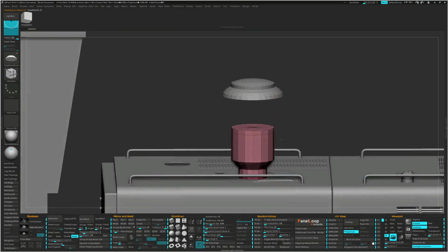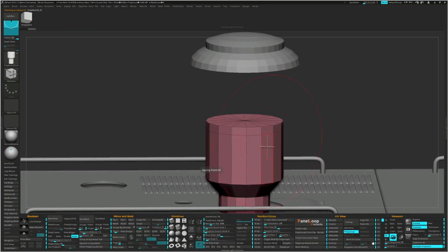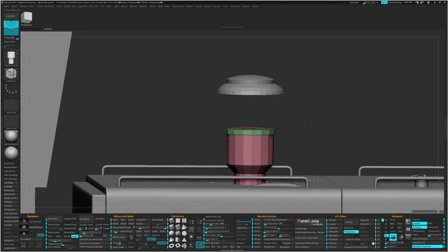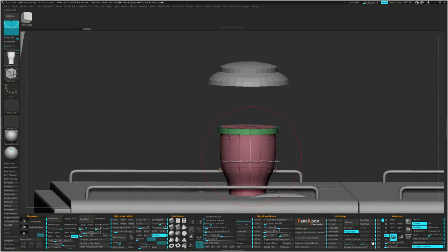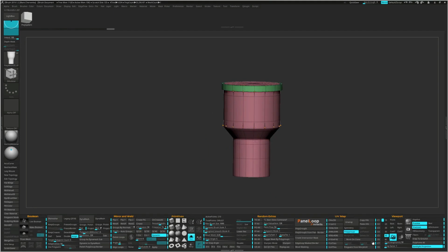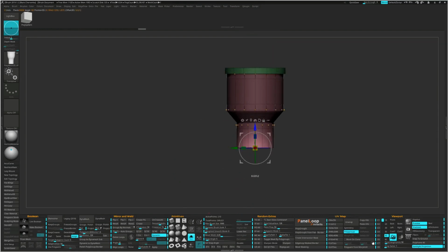Select the base and pull out a poly strip. Turn on dynamic and use edge loop this time instead of the crease level. When on the same subtool, sometimes you need a different falloff for the edges. It is better to use edge loops to control that. Otherwise, you can use dynamic with crease levels for consistent roundness of the edges.